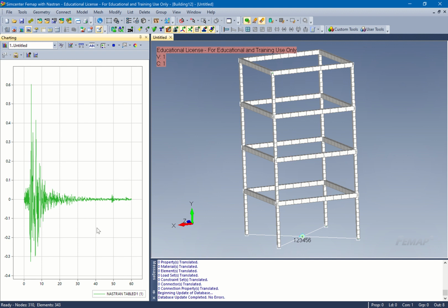One would be time. They're almost always digitized to 50 hertz, so the delta T is 0.02, I'm sorry. That's the standard because the frequency content of interest is low; if you digitize any higher, it's the same. Plus, there are thousands of records every time there's an earthquake. You can download it from almost anywhere in the world.